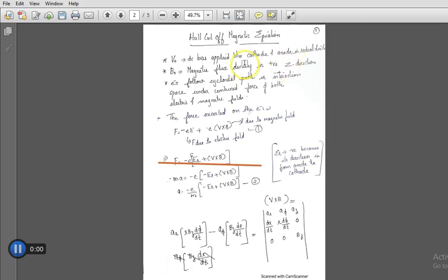The figure which we are going to look into is the same figure of the cylindrical magnetron. At the center we have the cathode, which has a radius A. That is what is shown here also. And around it we have the anode, which has so many slots, and each of the slots acts as a resonant cavity, producing the RF signals or the noises. The cathode is connected to the minus terminal of the beam voltage V0, and the anode is connected to the positive terminal of V0.